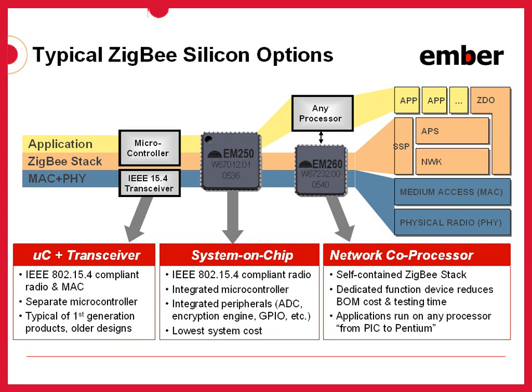Depending on the implementation, the NCP firmware may also expose additional features or abstractions of stack behavior that accomplish higher-level application tasks tailored to the kind of application being run. So this would be similar to an ASIC. NCP providers may provide multiple firmware images targeted to different kinds of host architectures, different kinds of serial protocols, or different application profile use cases. For a more detailed examination of these options, including specifics about Ember's platform relative to these areas, refer to the training section entitled Ember Platform Overview and Support Resources.